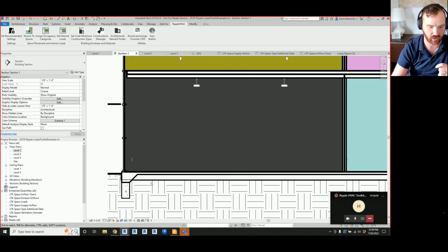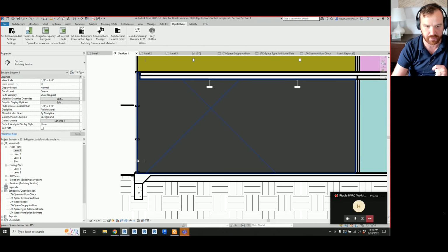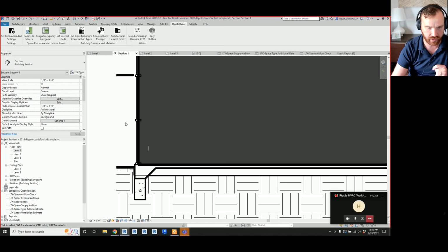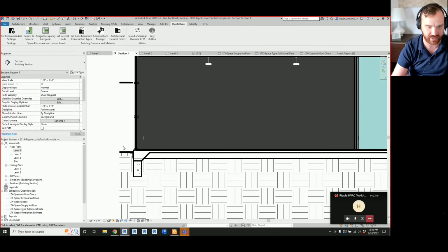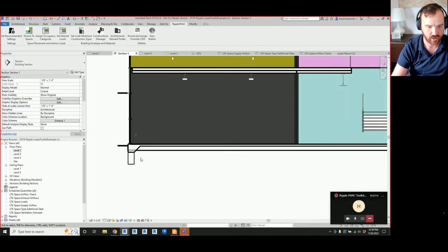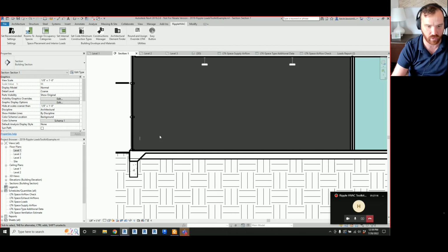It will not calculate a load to grade. When this engine was built, ASHRAE with the radiant time series method didn't have a calculation procedure on how to do this. So they don't account for heat loss through the floor.